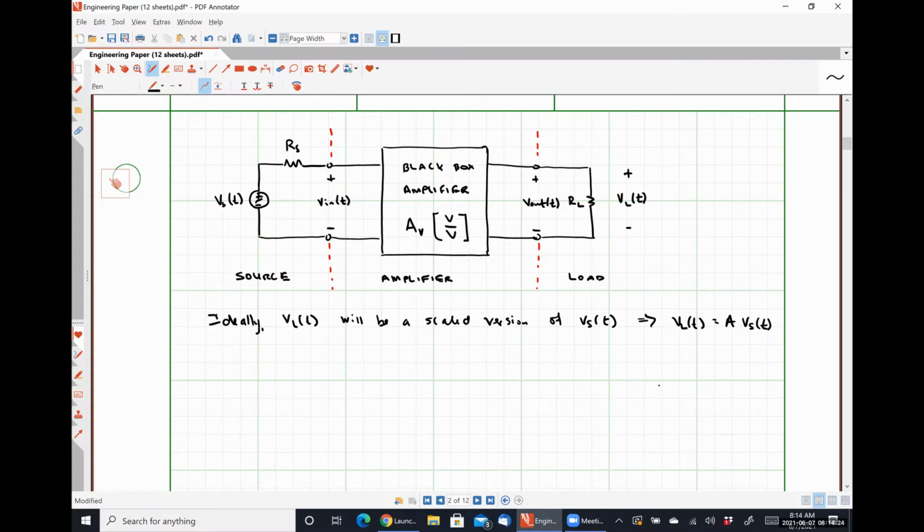Are you putting the load? Sure. We'll see a Thevenin and Norton equivalent circuit. We're looking in. What do we see? We have no source, so we should see a resistance, right? If we have some black box connected to a voltage source and we disconnect it from the voltage source, look in, we're just going to see a resistor, okay? We have no reason to believe there is anything else, at least looking in from that direction, right?